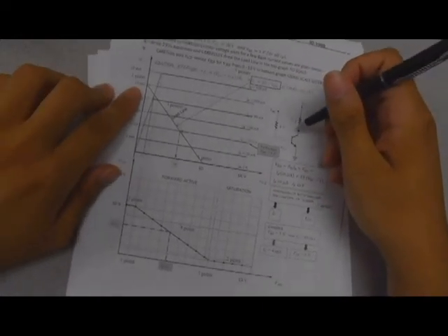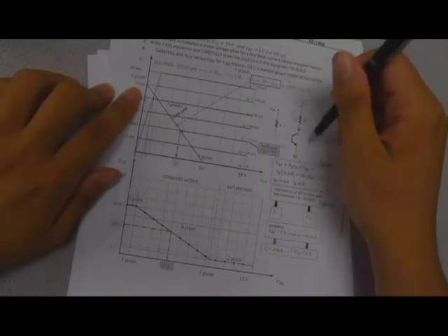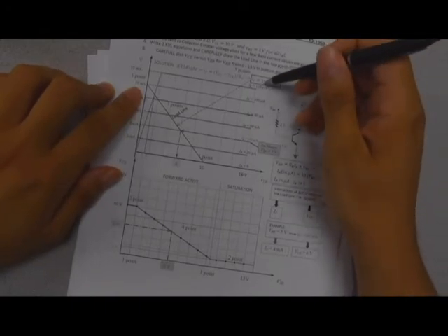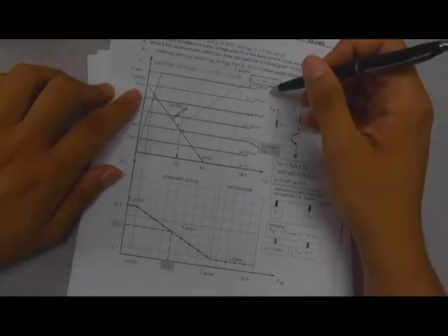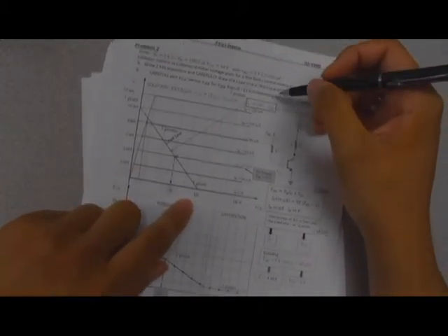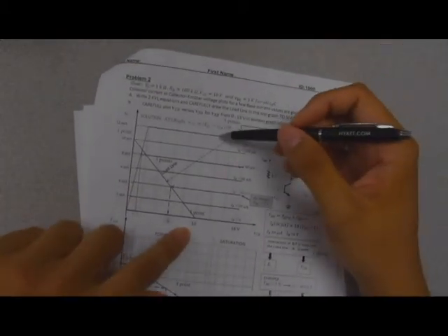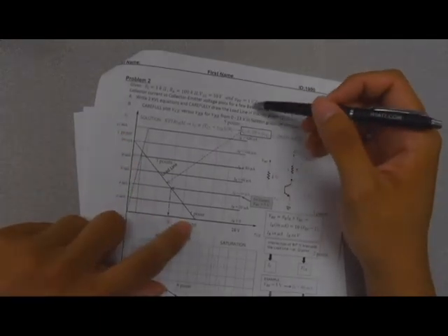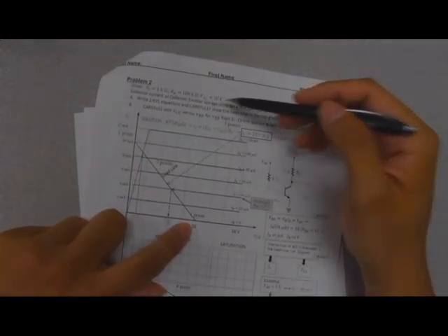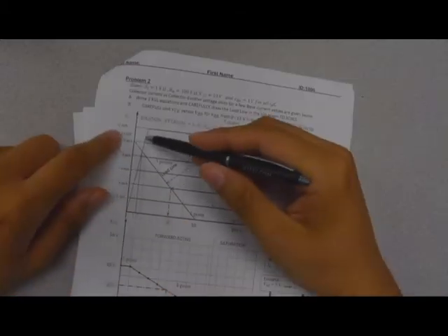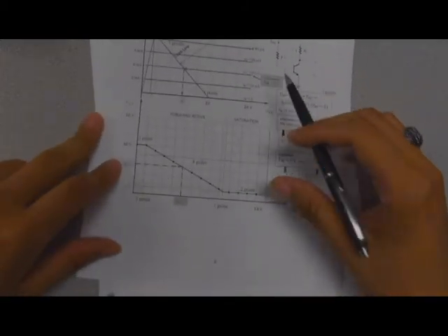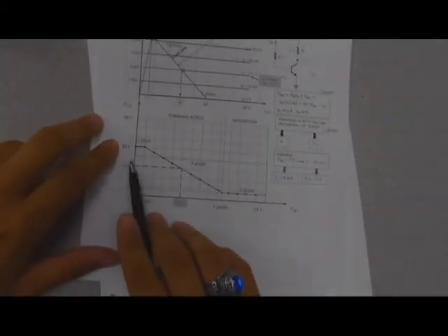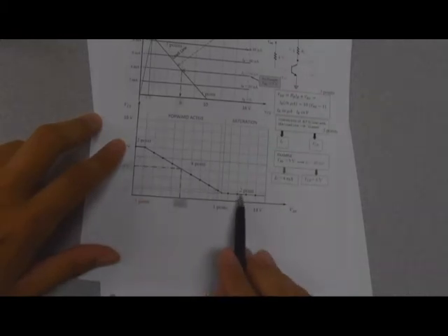And what you're going to do is calculate the fact that IC going around this loop is going to be equal to 10 milliamps as a function of VCE. So VCE is going to vary between 0, where it would be 10 milliamps, and 10 volts, which is the limit on that VCC source. So then you can draw the load line, as well as draw the different regions where you are in your forward active or in your saturation region. But we'll let you guys handle that on your own.